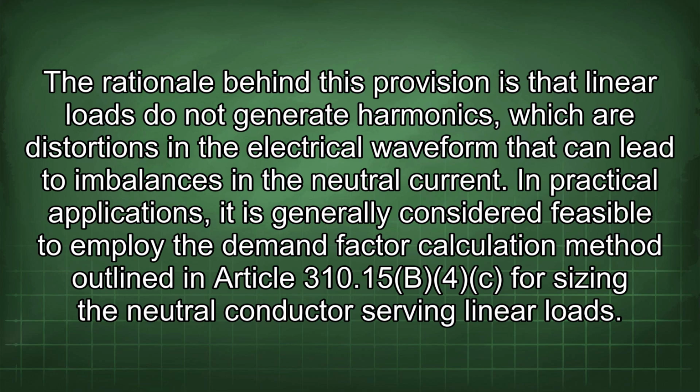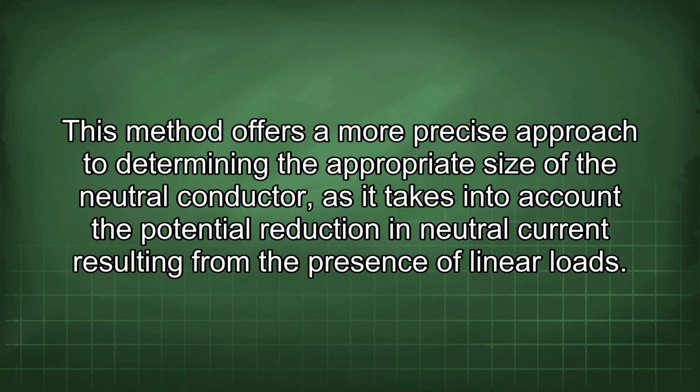In practical applications, it is generally considered feasible to employ the demand factor calculation method outlined in Article 310.15(B) for sizing the neutral conductors serving linear loads. This method offers a more precise approach to determining the appropriate size of the neutral conductor, as it takes into account the potential reduction in neutral current resulting from the presence of linear loads.